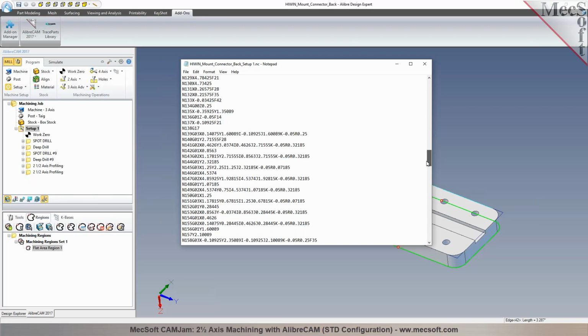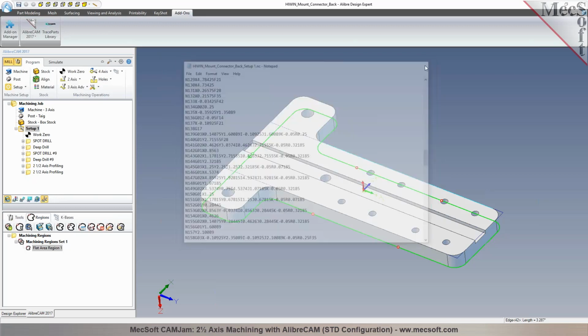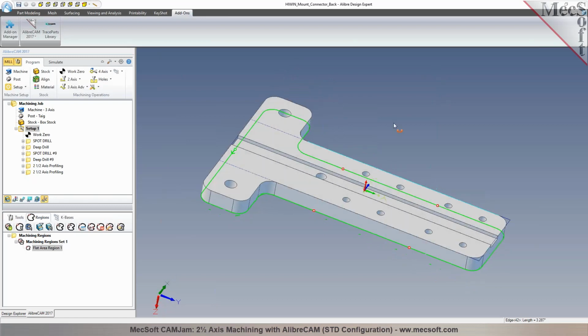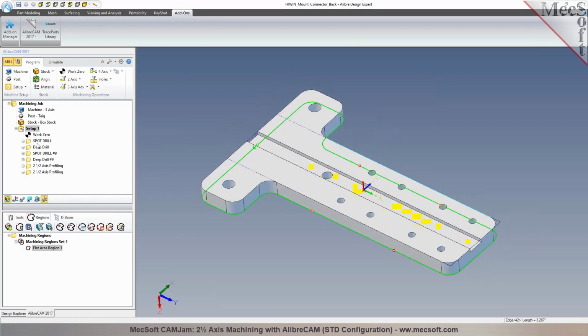Okay, so now what happens, how well integrated is it, if I change the CAD, how does it break the CAM, and how do I regenerate something, like if I change the size of a hole or something? Well, in some cases, you'd have to go back and just reselect the geometry, repick the face, for example. You may have to reselect the tool, redefine the stock. The operations would still remain.